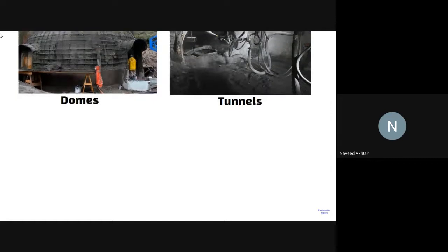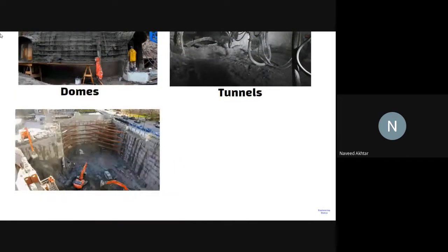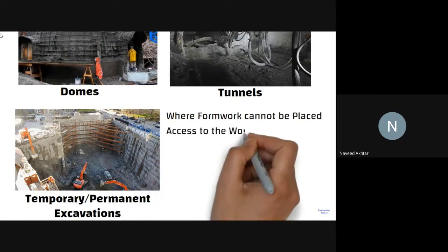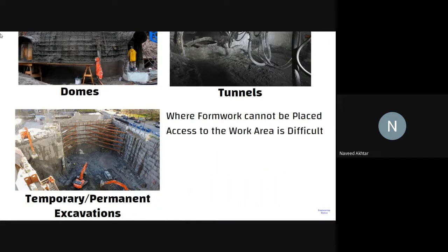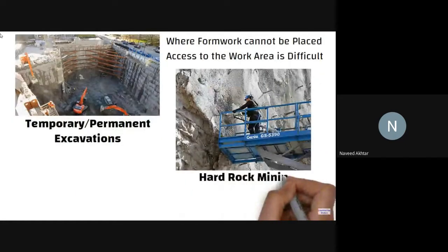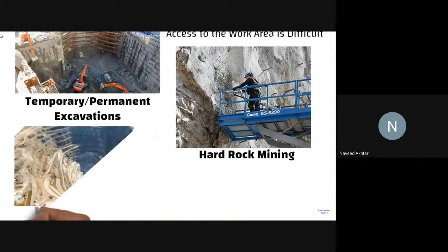It is best suitable for dome construction, tunnel construction, and for side sheet piles, etc., for excavation where normal concrete cannot be placed. You can apply shotcrete, and that is very good in places where the normal concrete technique is not possible.